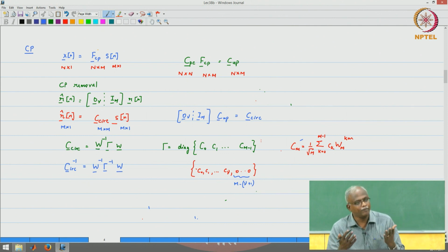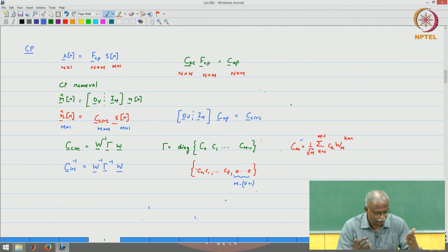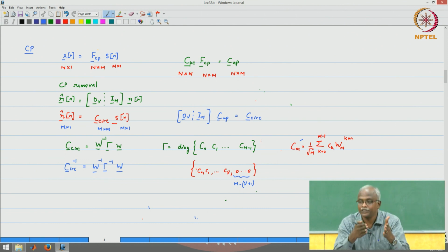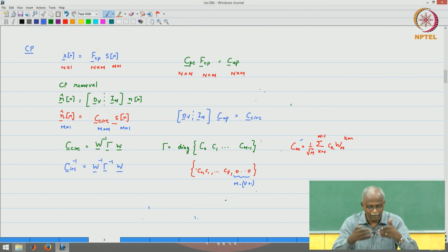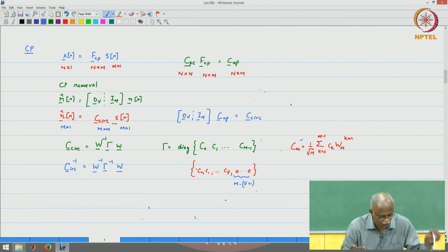It's equivalent to the MMSE approach, rather than doing zero forcing, you find the solution. But the reason we say that it does not affect us is that it will happen on a particular sub channel that has low SNR, and you would not have done any transmission on that channel to begin with. So really what happens there is not going to affect us.